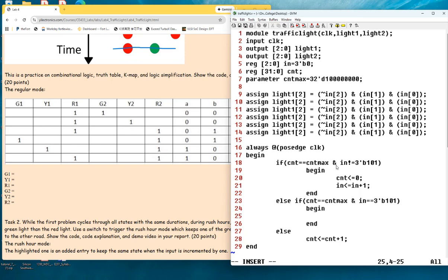Yeah, but five also deserves a time, right? It's a state. The light needs to stay at that state for a second. And it gets into the always block at every rising edge of the clock, which is running at 100 megahertz, so it's actually almost all the time. So you need to let it count to 100 mega. Okay, I guess it'd be the same. Or you could make your initial if go to 6 and just skip the count, but I guess either way. Yeah, either way you can try it, but I think this will work as well.